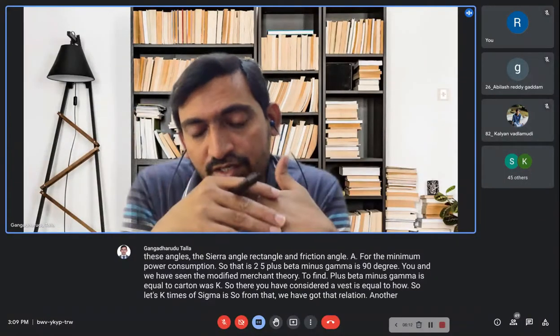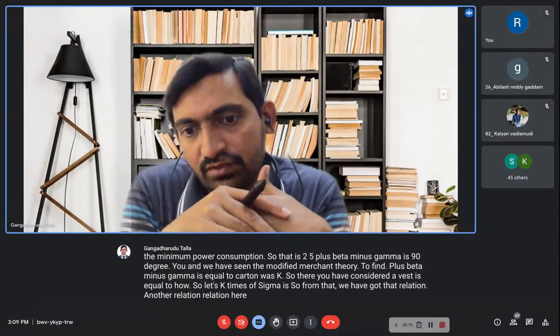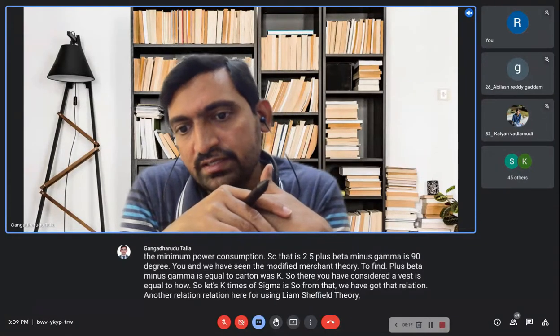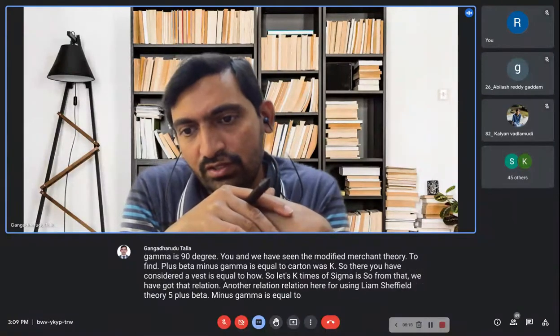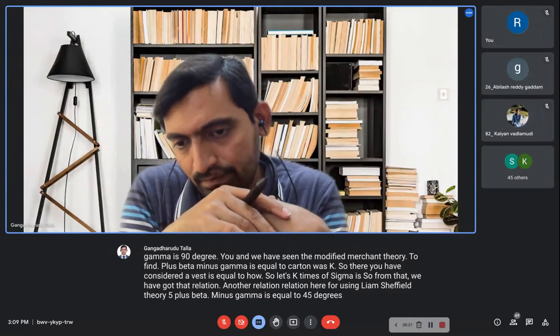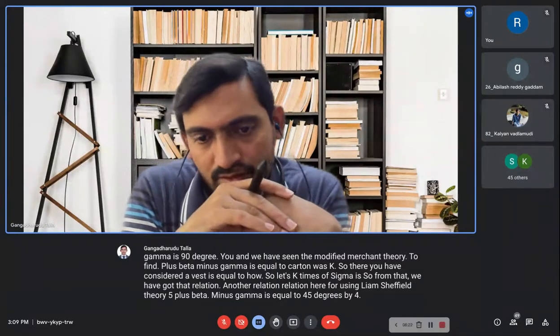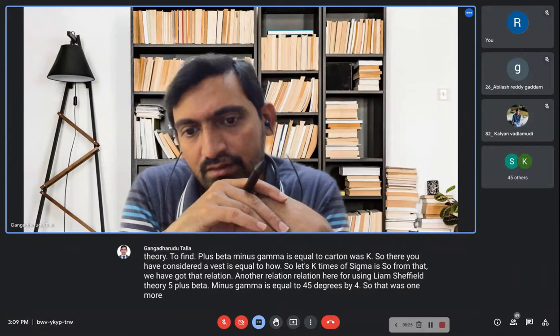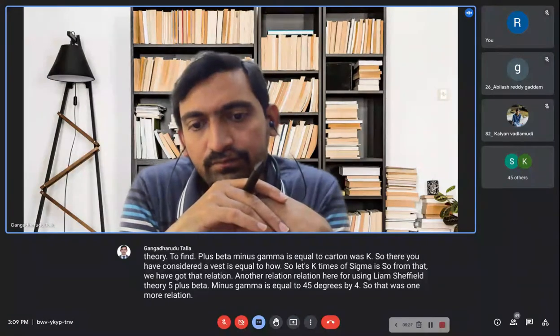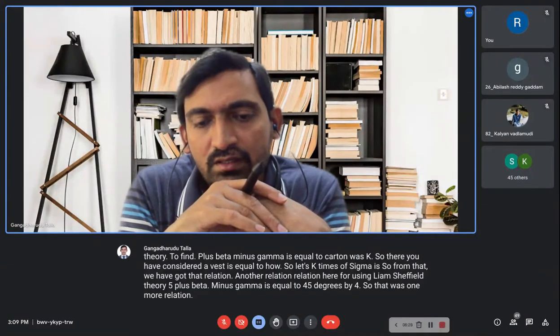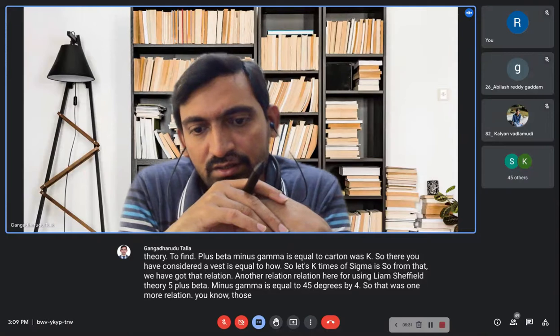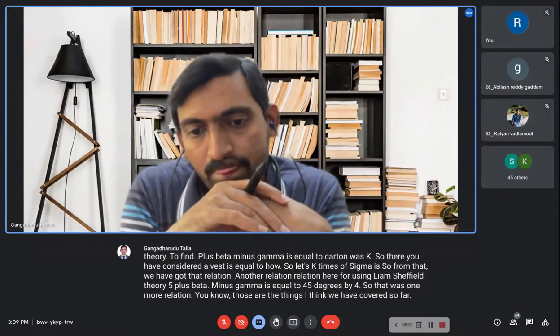Another relation is Lee and Shaffer. Using Lee and Shaffer theory, phi plus beta minus gamma is equal to 45 degrees, pi by 4. So that was one more relation. Those are the things I think we have covered so far.